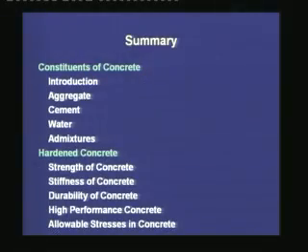Another very important criterion of hardened concrete is durability. As a concrete structure ages, the cost of maintenance and repair can be substantial. In order to limit this cost, durability issues are being emphasized at present. In IS 456-2000, there is a separate section on durability, which is quite comprehensive. It is expected that the prestressed code IS 1343 will also be revised to have a more enhanced section on durability. At present, IS 1343 provides the durability requirements in the appendix.